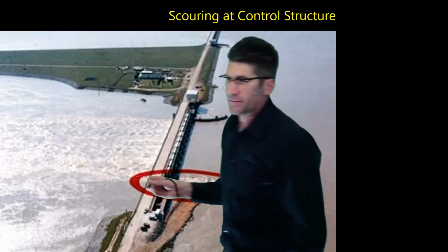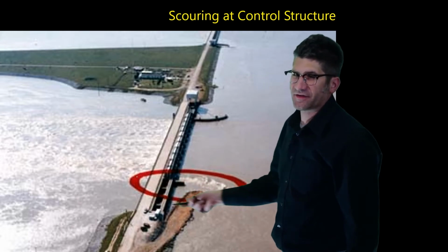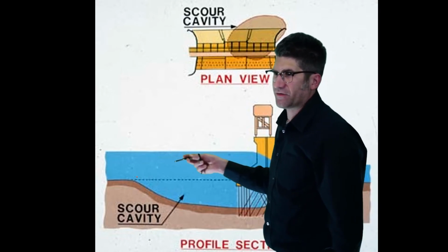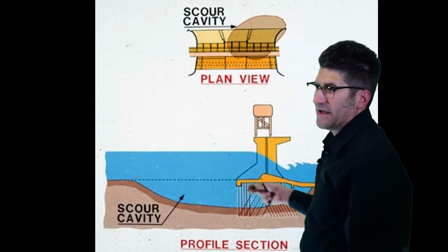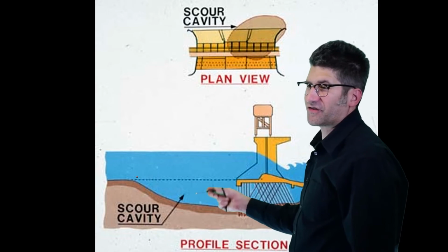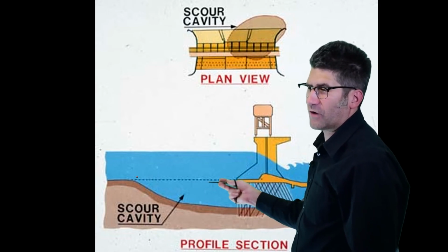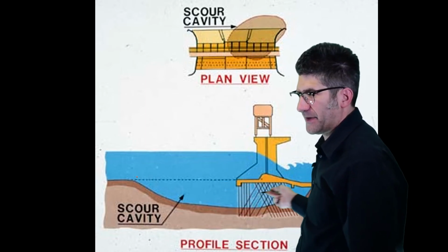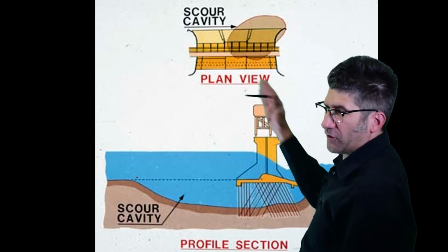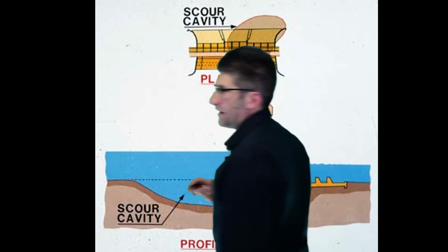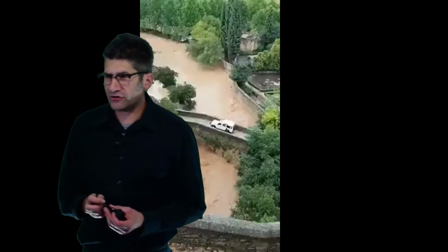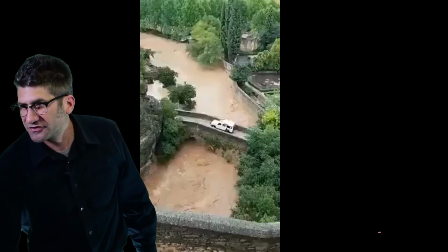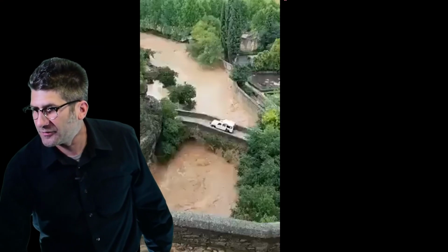You can see it in red here where we had significant scour of the structure. And so that we were cutting underneath. And so this is common along rivers, is that when you have structures, you'll get scour along the base of them through vortex flow, and so you scour out the base. And so if this thing had failed, the whole thing would have collapsed. So I've got a little movie here to show you what scour can look like when you're scouring along a meander bend, which is essentially what happened in the Mississippi River here.